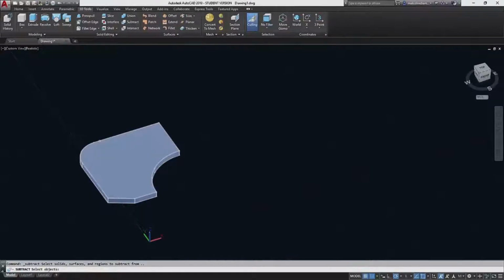Well, we left click this outside shape. Okay, once we've done that, we right click, and immediately we're asked to come in and select any shapes like that one and that one that we want to subtract, and then we hit the right hand mouse key and bang, they're gone. Okay, now that is around about as simple as it gets.